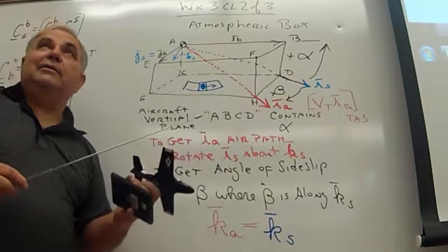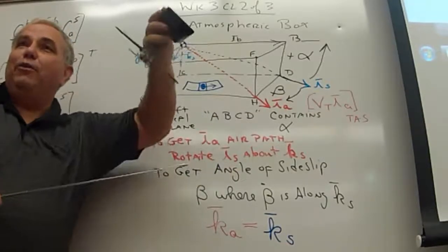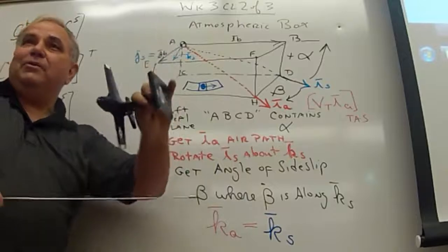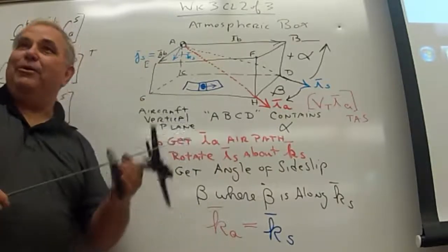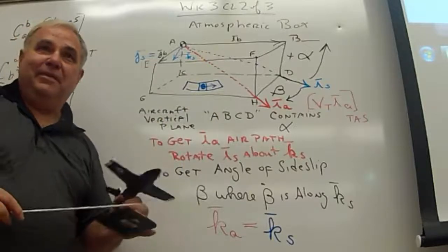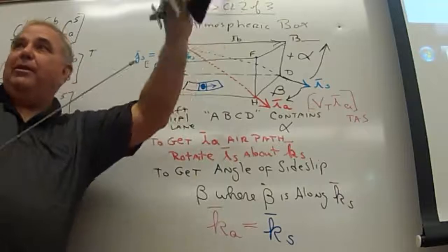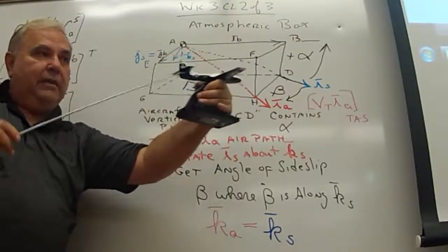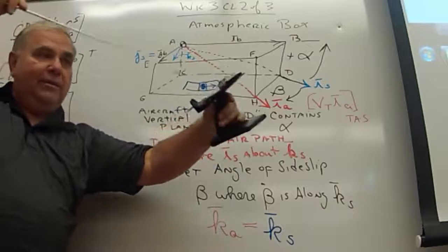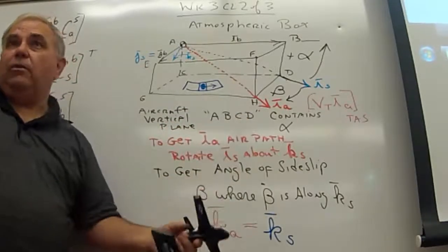I mean, where it's actually too controllable. It's too stable. It enters a maneuver so stable that you can't get out of it. So a spin is actually too stable of a maneuver. You enter a maneuver you can't get out of. We call it uncontrollable, but uncontrollable would be kind of like flailing around. A spin is a maneuver that is tightly constrained by how the aircraft is moving, but the flight controls aren't having any effect to get it out.